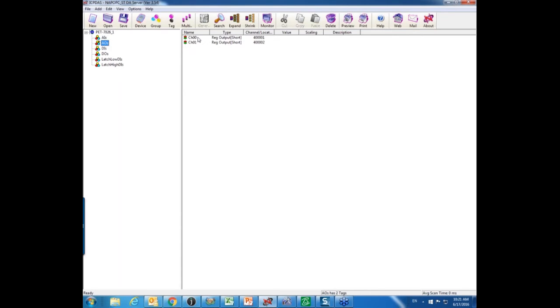Okay, let's open MiniOS7. The first thing to do is the configuration of the remote I/O module. I use the MiniOS7 utility to set my IP address, subnet mask, and gateway for the module. We will do a search in the MiniOS7 utility, and the result will show the remote I/O module that is connected, and then click IP settings.